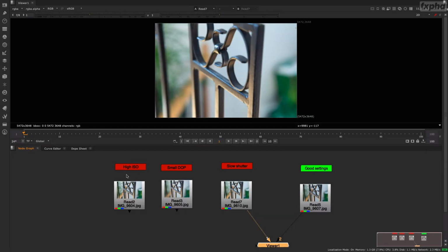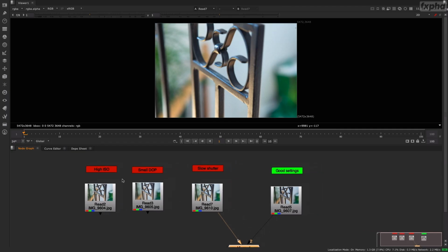Obviously there are three important settings when doing photo. The first one is the ISO setting, the other one is the aperture of your lens, and the other one is the shutter speed of your camera. Each of those settings will greatly affect the result that you'll have in Metashape. Having the optimal settings will really help you to have the best geometry out of Metashape. So let's take a look at how those settings affect the solving of Metashape.